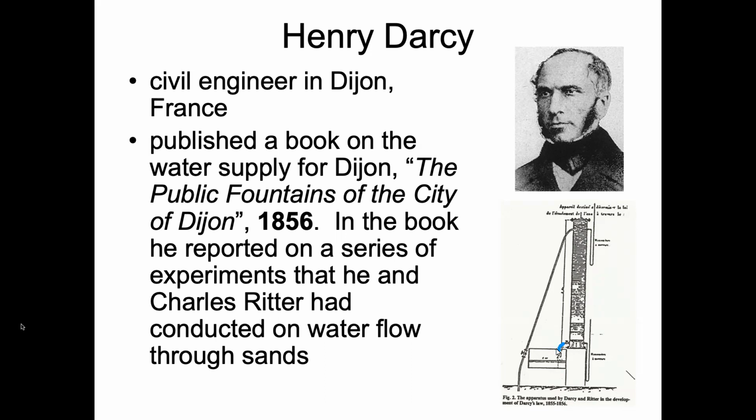We have water flowing out of the bottom as a volume of water per time, which is our discharge. We can also think of that as a length cubed, so cubic meters per second, coming out here. We have the column of sand, and then water is being put in on the top to create some kind of hydrologic head in this system. That may change depending on the design, but that's what they used in this experiment to derive Darcy's law.